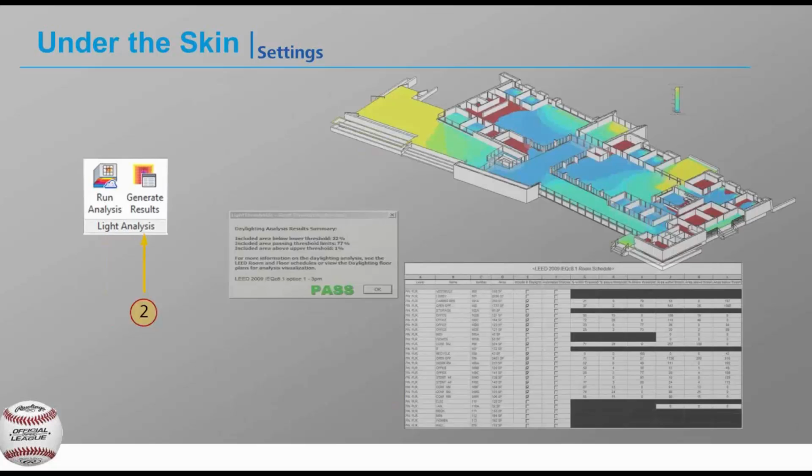Sorry, while I'm in this dialog, the environment settings, this is the location there you see is chosen from your Revit project location. And then the date and time are set for the analysis type, and we automatically look up the solar values. You can see there that the weather file values that we're using are listed.